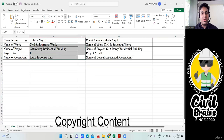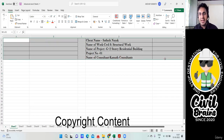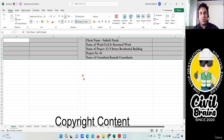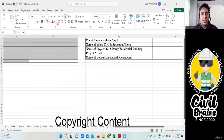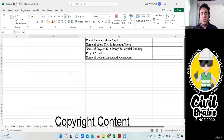Now, if you don't want this, I'll delete everything. Now what I can do is merge everything. I'll select this and say merge and center. Let me try to do that. Okay, it won't work out. Not an issue. I'll take out all these borders again. See, now you put this border, isn't it? If I don't want that, again, you select everything in this way. Go back here. There's an option called no borders. Select no borders. All the borders will go now.